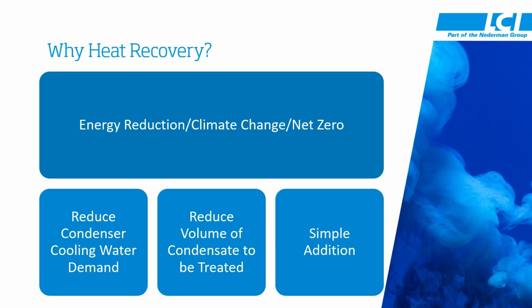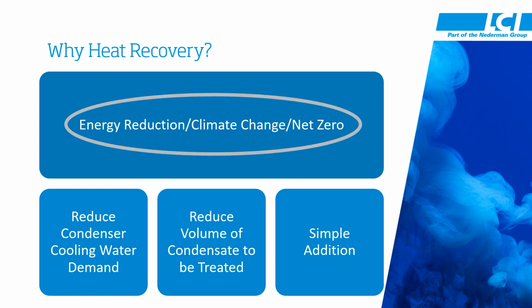So why would we consider heat recovery? Well, dryers are energy consumers requiring heat for the drying process. Due to climate change, it is important as ever that we consider energy reduction in net zero processes. Additionally, heat recovery can reduce the volume of condenser water required and reduce the amount of condensate sent back to the plant for treatment. These can also reduce the energy consumption of a wastewater plant. Finally, it's a simple addition. It's easy to add on to the drying process. But today we're going to focus on the energy reduction side of heat recovery.